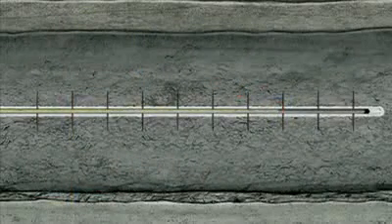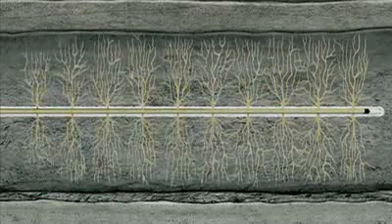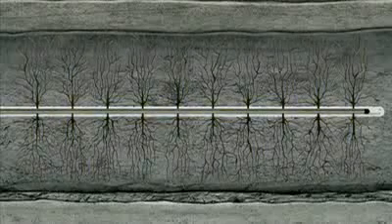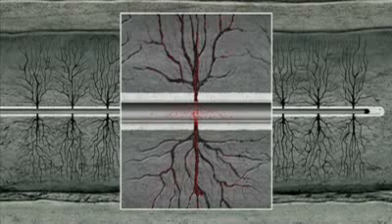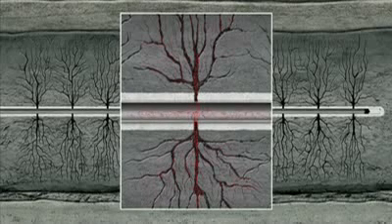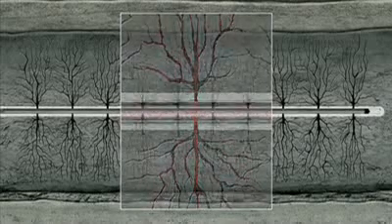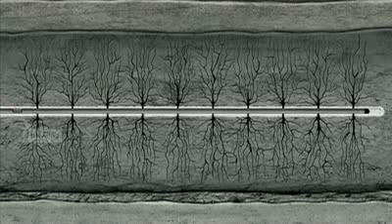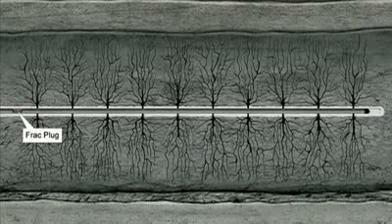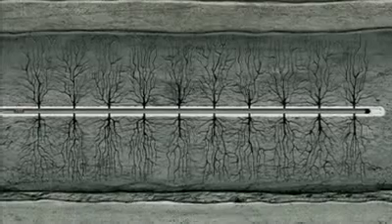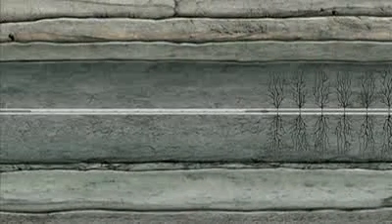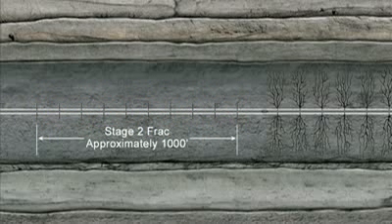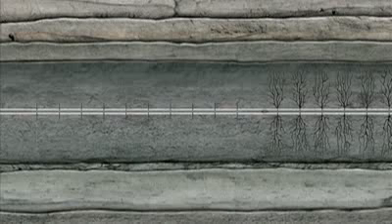The gas must be stimulated to flow by fracking. This requires water, proppant like sand, and additives to be pumped into the wellbore under high pressure to the point where holes have just been made into the rock formation. The mixture is forced out through the perforations and onto the surrounding rock where it should fracture in the shale. Hopefully fractures are created that will provide a route for the gas trapped in the rock to flow into the well. Next, a temporary plug is placed to close off the perforated section of the wellbore.